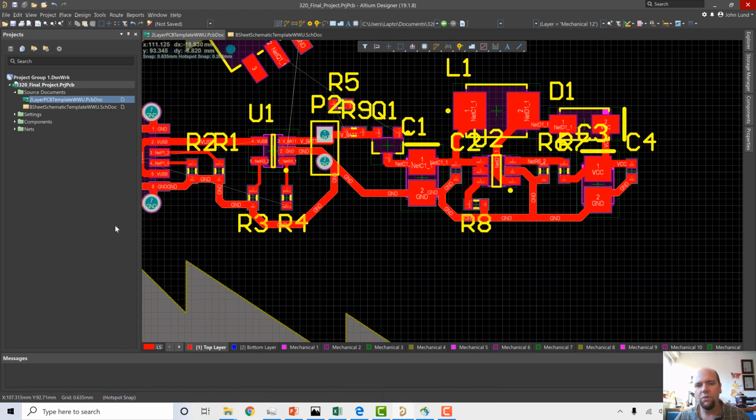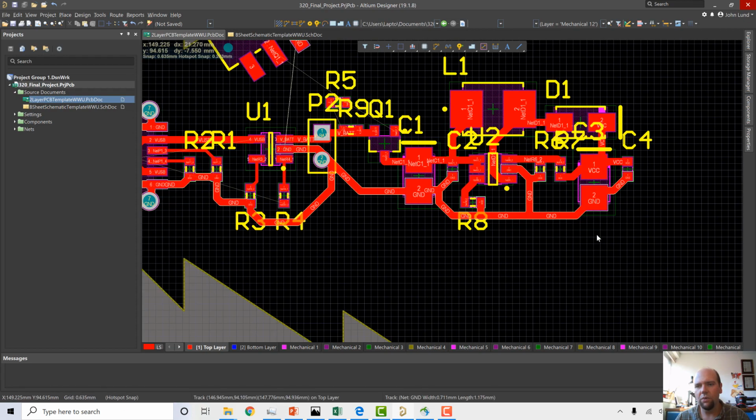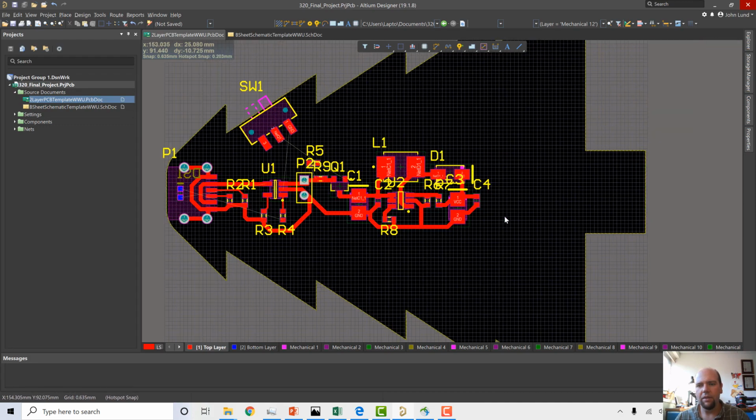And normally we would probably make this ground path a nice fat ground plane, because we really like to minimize the resistance on that ground path there. But this circuit that I'm building, it's not a huge concern. It's not a huge size issue, so I'm not going to worry too much about it. But the main thing is our power inlet's over here. Our power outlet is right here.